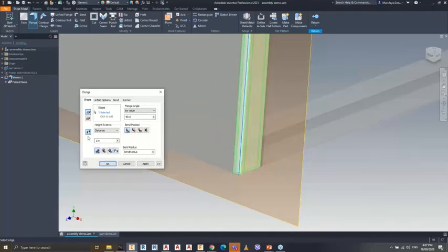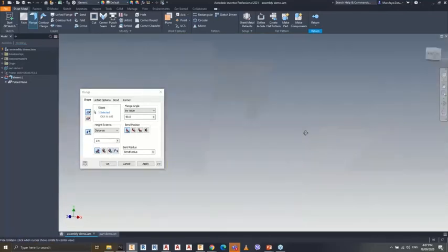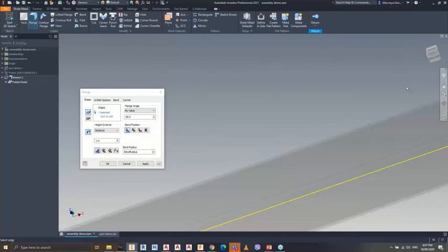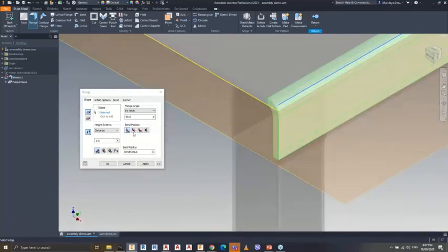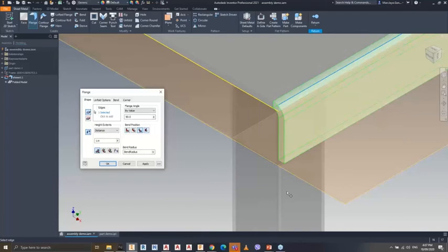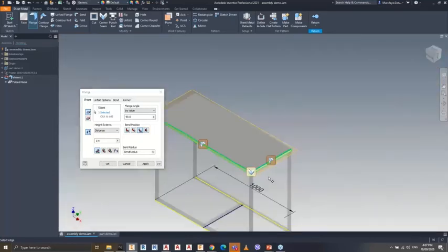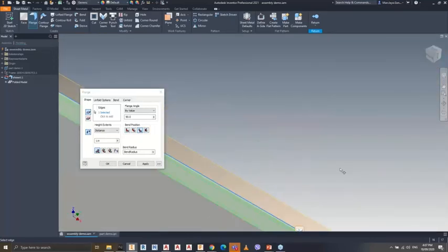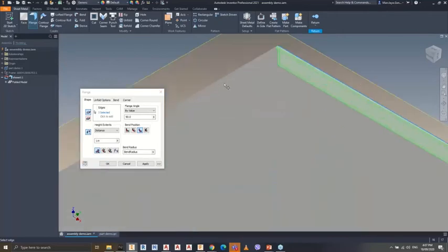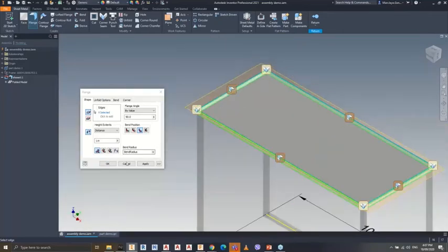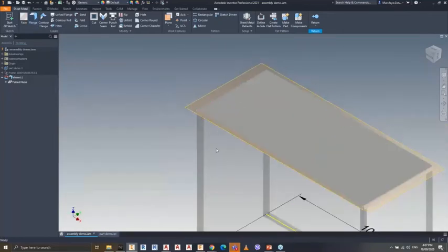And you can flip it, okay, on the other side if you want. And you can also adjust, okay, the behavior of that bend, okay. And you can also select those edges for you to automatically create bend on those areas, okay. And then simply click on OK.